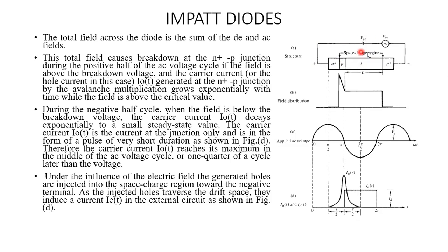But those electrons are going to move in this entire sample only if the holes reach this point. So if the holes are moving here, then the electrons entering from here will start moving and current will be set. But this process will get delayed. By the time the holes reach the anode side, this cycle reverses and reaches, suppose, this peak value. And at that time a pulse is considered to exist in the external circuitry.